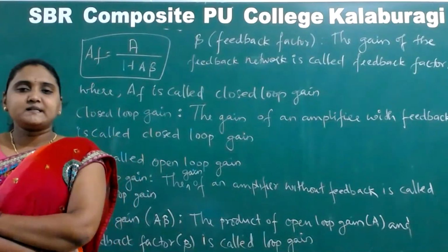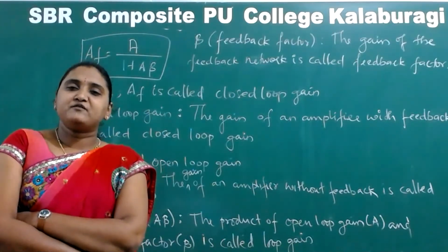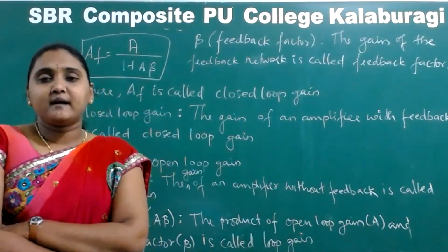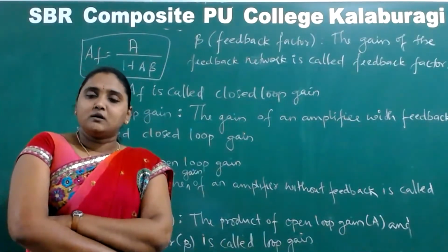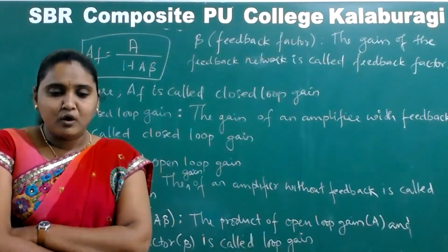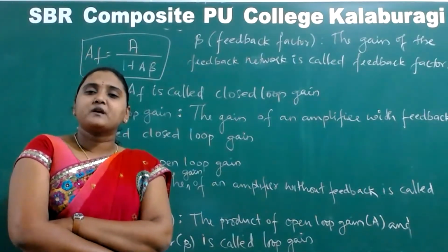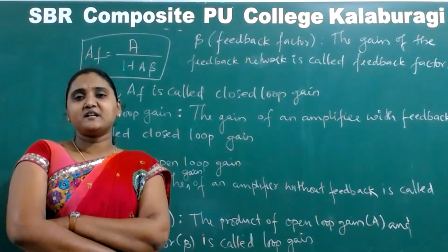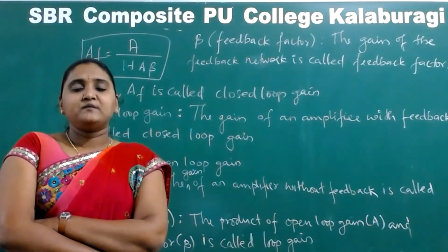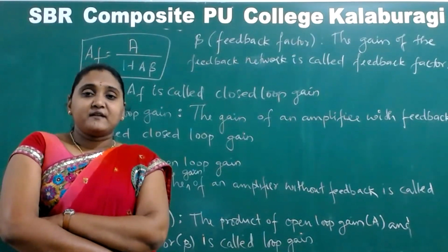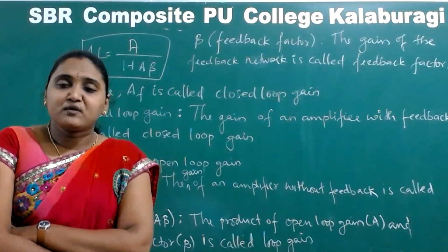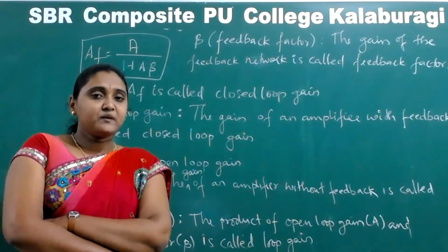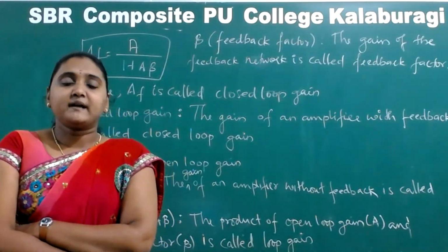So what all we have discussed, starting with the definition. From the definition we moved into what is a feedback amplifier. The amplifier with feedback signal is called as a feedback amplifier. So we saw the two types of feedbacks, positive and negative feedback, their advantages, disadvantages and applications we saw. And there we have seen that the positive feedback is used for the oscillators, whereas the negative feedback is used for amplifiers. Proceeding with the negative feedback, because we are studying feedback in amplifiers.